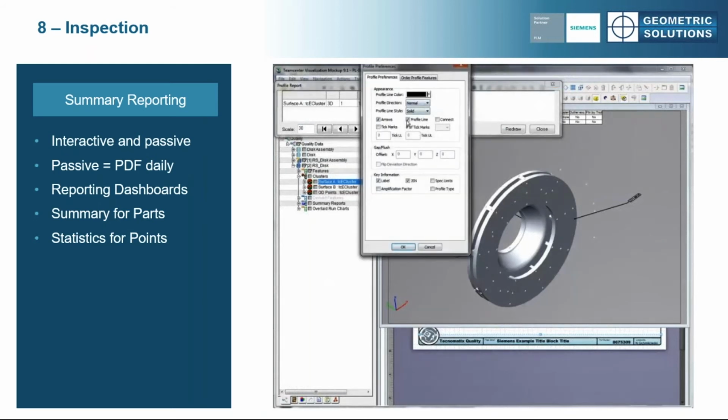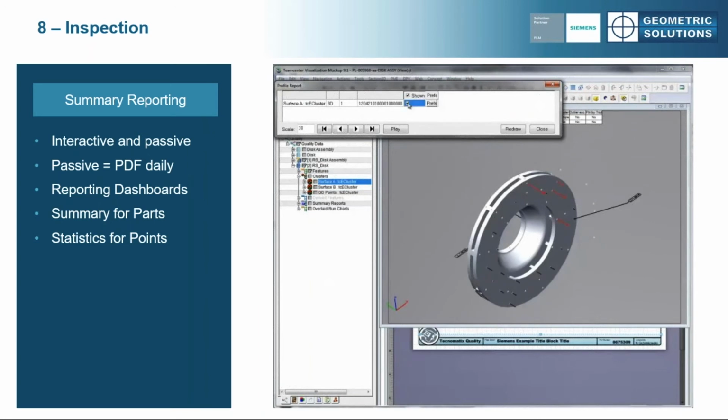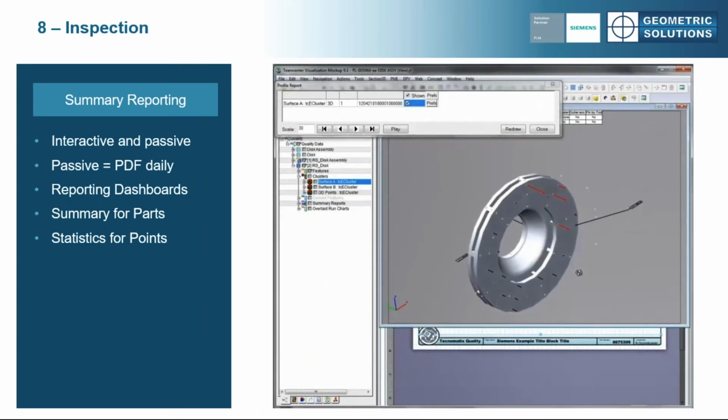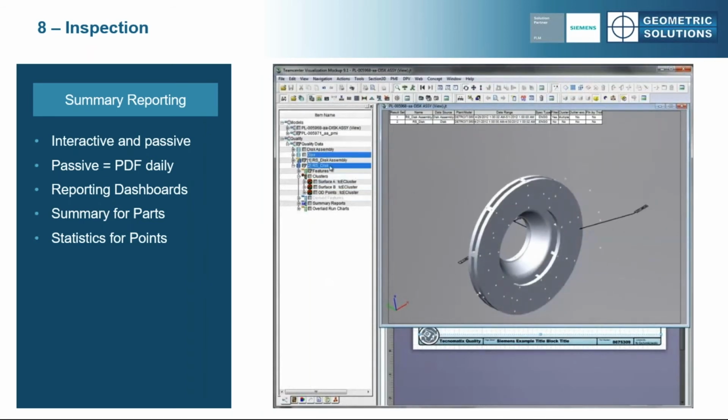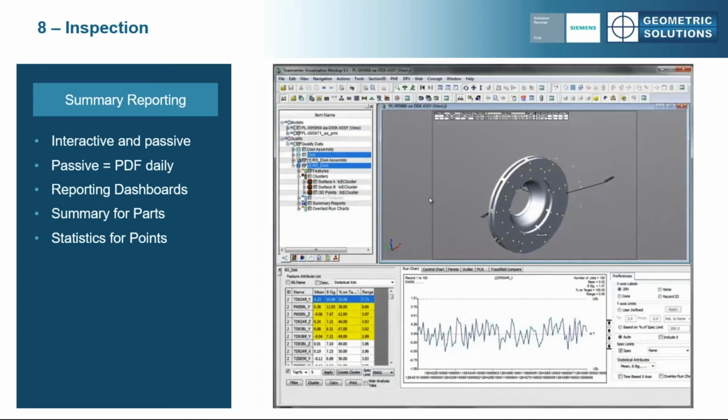So here I'm going to grab a 20-part sample, and I have a couple of choices here. I'm turning it all on and off to make sure I get the rate I want. And I hit OK, and I can actually get the data to show up on screen. And you can see those arrows, the red arrows and the black arrows, showing me order of magnitude. The length is just kind of showing me where it is. And you notice the reds are all in that northeast corner of the part. So something's going wrong. It's coming out of spec.